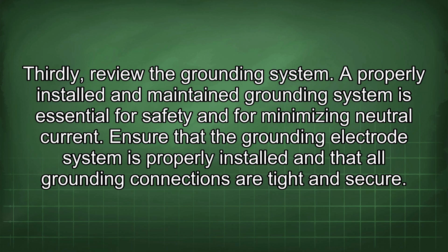Thirdly, review the grounding system. A properly installed and maintained grounding system is essential for safety and for minimizing neutral current. Ensure that the grounding electrode system is properly installed and that all grounding connections are tight and secure.